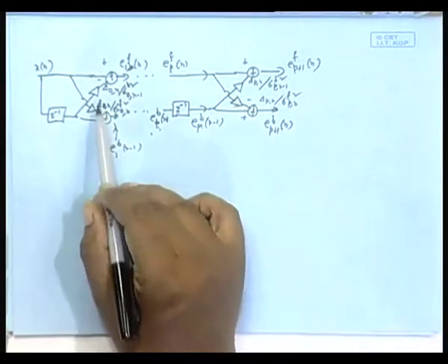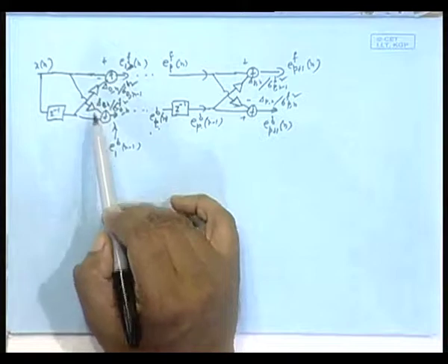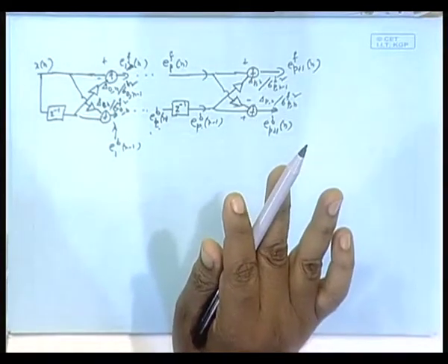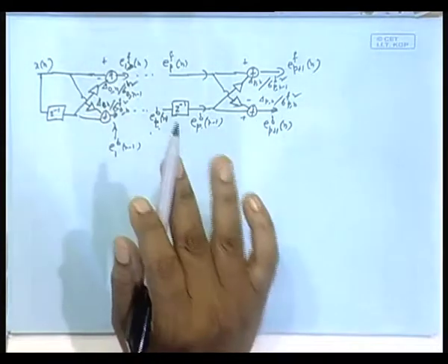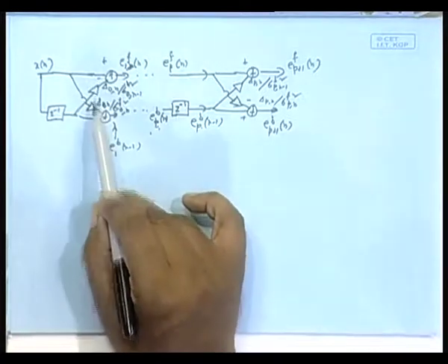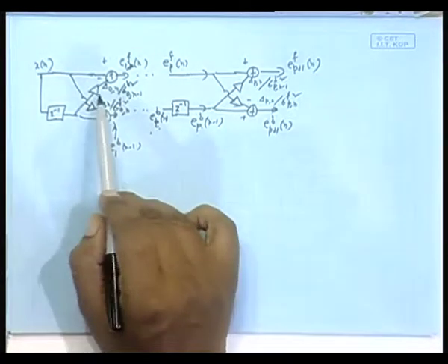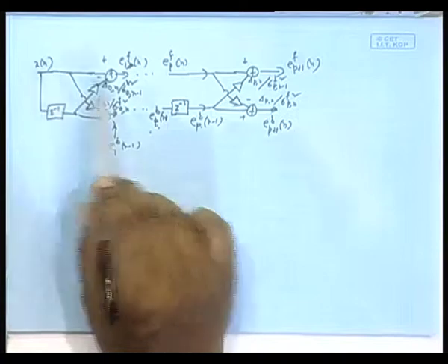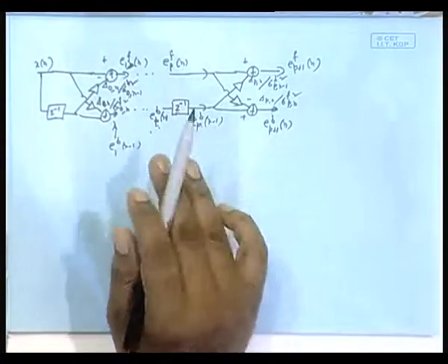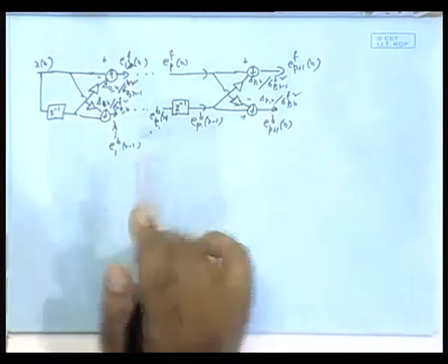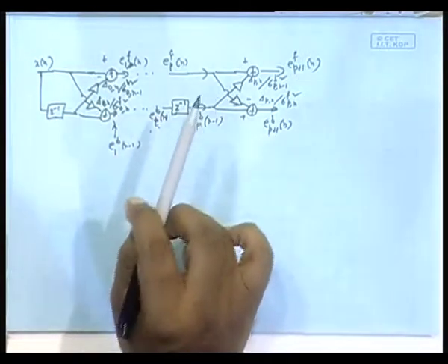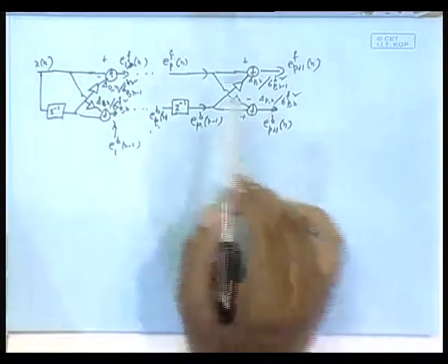So once you know the parameters at any index, all the coefficients are time dependent. Unlike that lattice, here all the coefficients are time dependent, and at each index n, when you find out the coefficients, then you use them to filter Xn. This EP, Fn, and these are only signals, these are not parameters. Once you know the multipliers, at that index of time, whatever signals you just go on filtering them, you get these various signals.